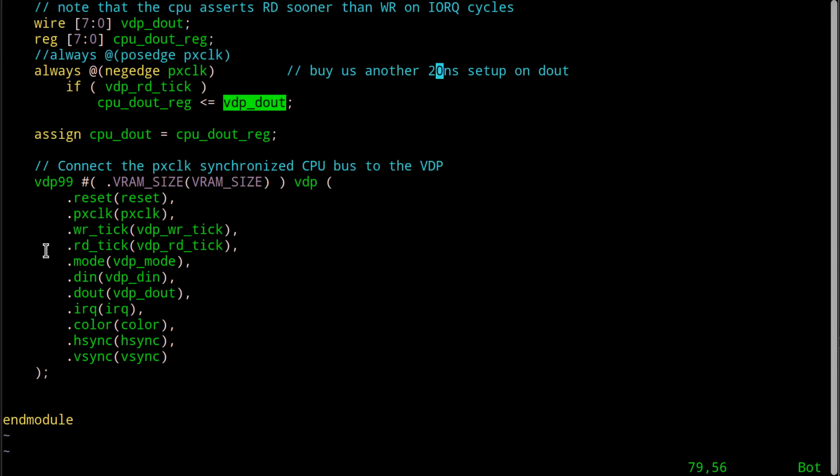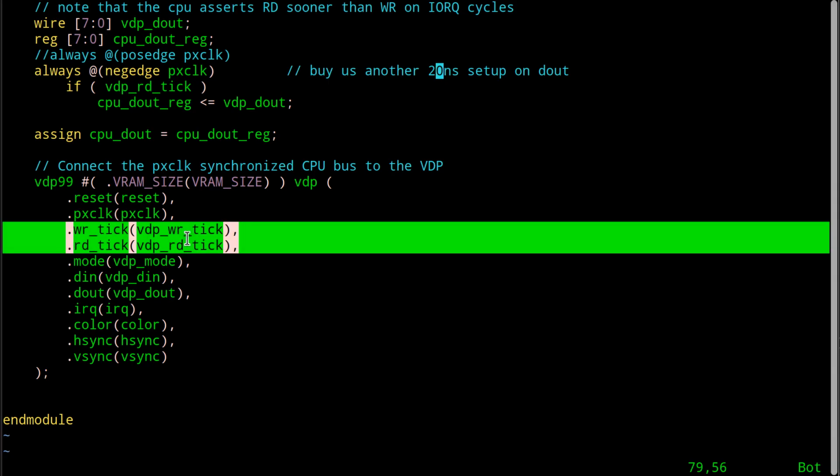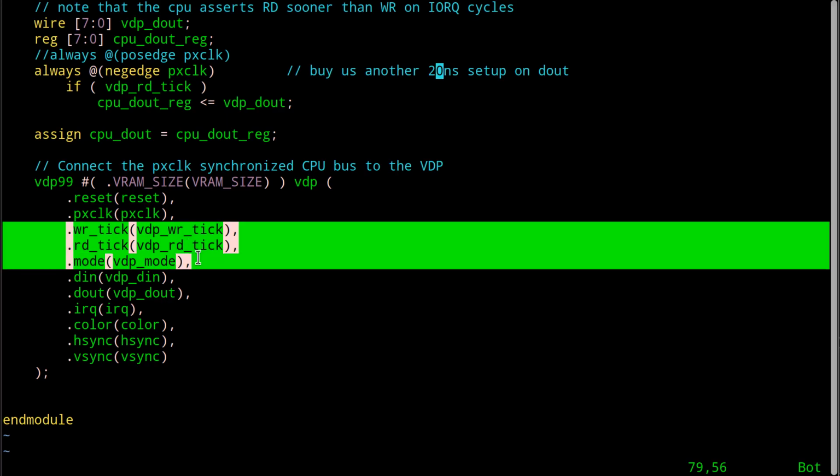In another video, we'll look inside here, and we'll look at how the registers themselves work inside the VDP and see where this actually comes from, which is the data out from in here. And of course, the short of it is, I would argue it's obvious. It comes from either the video RAM when you're reading the video RAM, or it comes from the registers that are inside the VDP, based on the mode and what you've done previous to the time you're reading from the VDP.